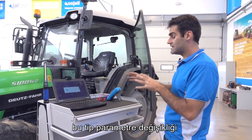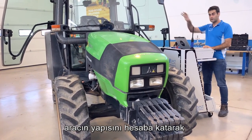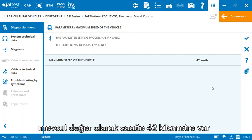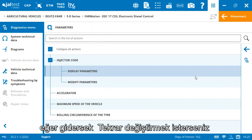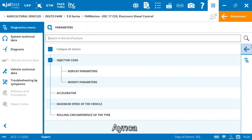So this type of parameter modification should always be done accomplishing the law, okay? Taking into account the construction of the vehicle. There we are. Now we've got 42 kilometers per hour as the current value in the electronic control unit, okay? This is everything in the engine control unit. If we want to modify it again, we will repeat the whole process and it will be done. The same with the rest of the parameters.